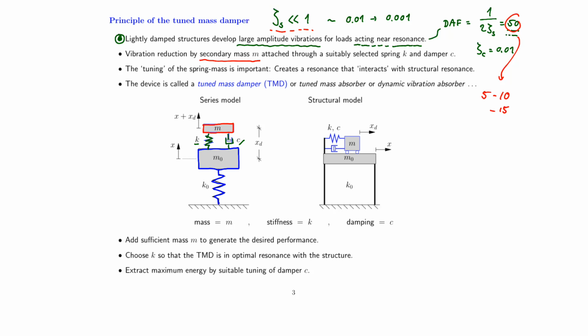So let's assume, for instance, that we have a shear frame building. Could look like this. And we want to damp the first vibration mode. We need to choose a particular vibration mode for our tuned mass damper. In many cases with environmental loading, it's typically the first vibration mode. So first of all, we would like to place the tuned mass damper where it has the largest amplitude to act upon, and that would be for the first vibration mode at the top floor.